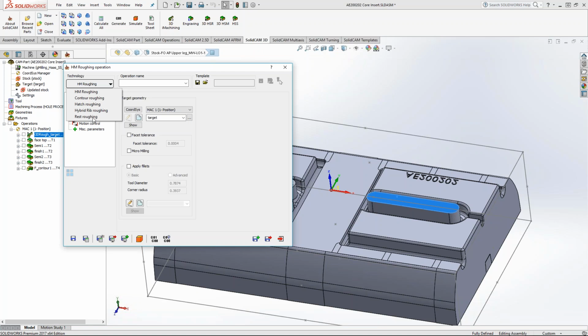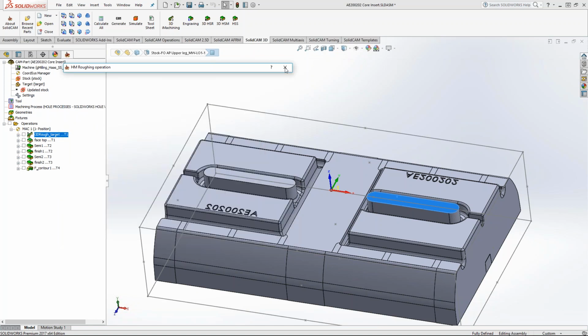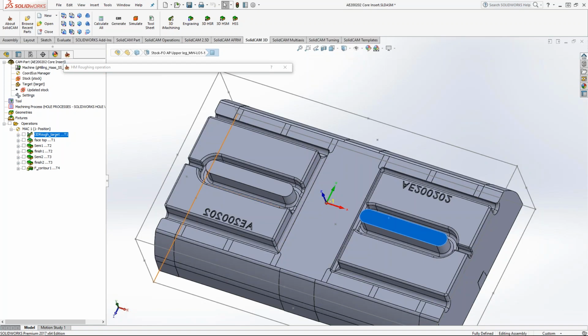This is the main one. Sometimes I use the rib roughing, if I had some small ribs that I want to put in there. And no, I don't think any of these has some ribs in it. This was actually a rib, but I was able to cut that with a 1/8 bull nose. I believe that's what I used on that one.